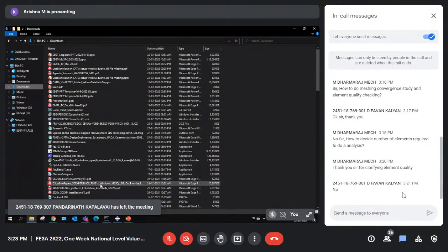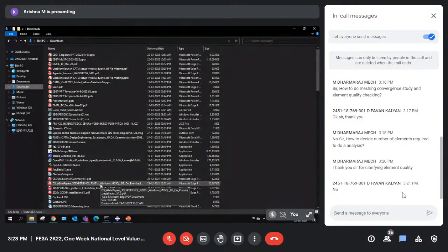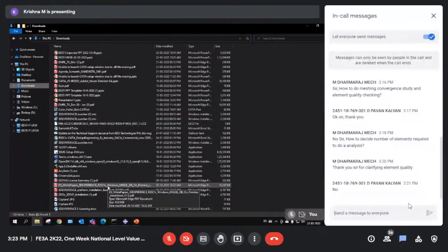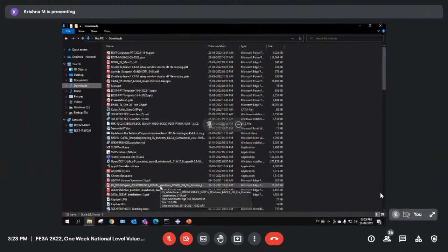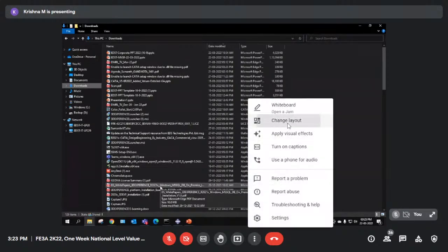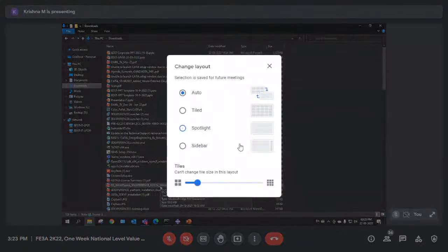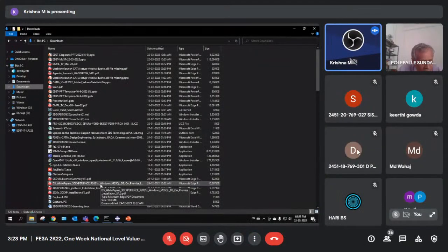No, I'm not asking like that, sir. Even within a single material, say for example you have taken a beam, at the bottom there is one property, and when you reach the top, there may be another property. Yes, that will come under material non-linearity. Normally there are three types of non-linearity. That will become a non-linear problem, so accordingly you have to give the non-linear material details.